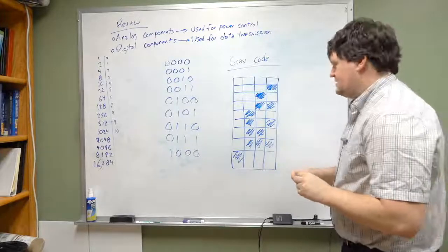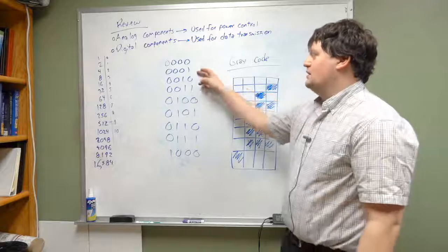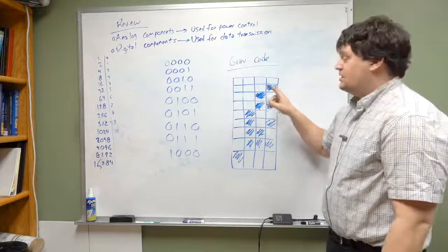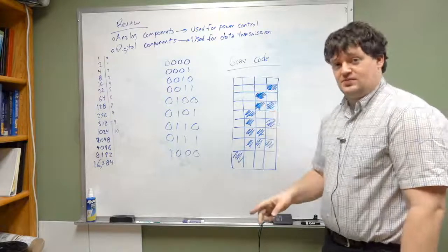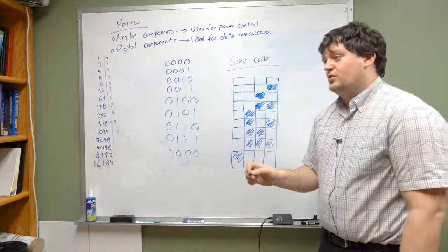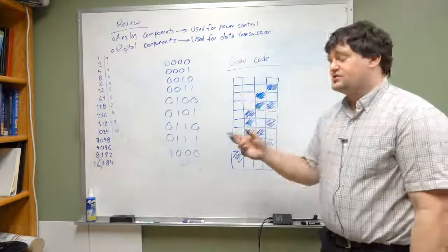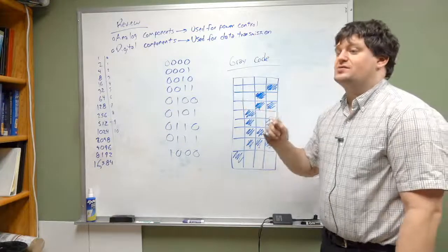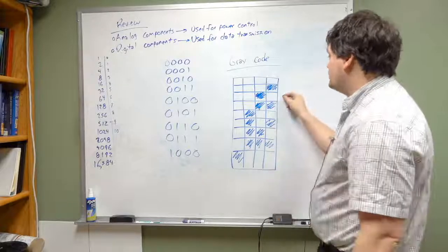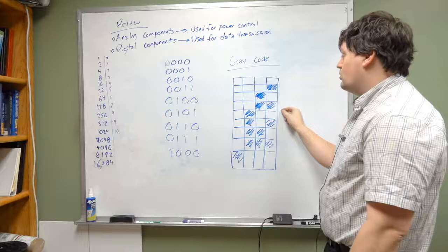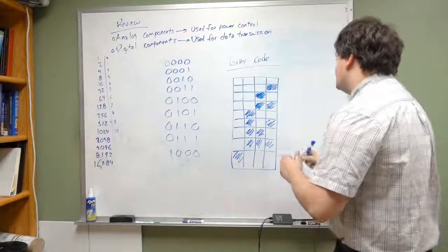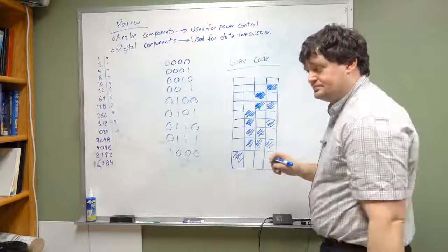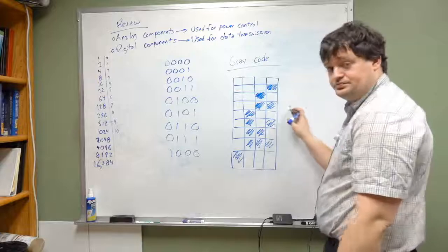Okay, in this system, in order to add 1, I have to shut off this wire and turn on this wire simultaneously. If in that moment my clock register occurs while this is in the process of switching off and this is in the process of switching on, I receive an error because it will either jump to 0 or it'll jump to 3. Okay, so if this one turns on before this one shuts off and then the clock reads it, it reads as 3 instead of 2.